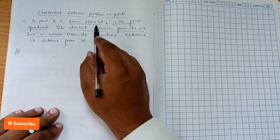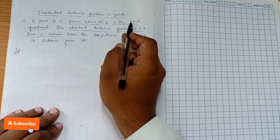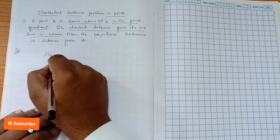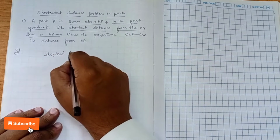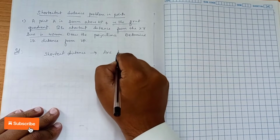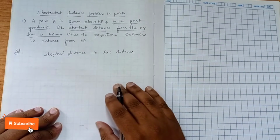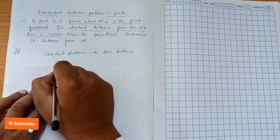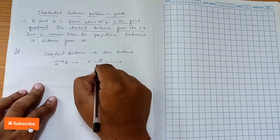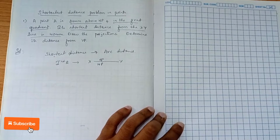In this problem they are mentioning only one view, that is the front view, and then they have given the hint that we have to consider the first quadrant, and then they have given the shortest distance. Shortest distance means arc distance, so we have to consider a compass here. We know that it is in the first quadrant, so VP is above the XY line, HP will be below the XY line. So we will proceed with the question now.